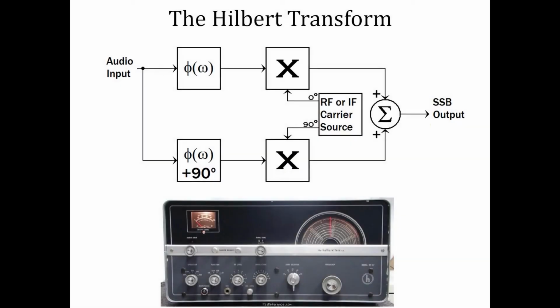It all has to do with the Hilbert transform. A Hilbert transform is an audio phase shift of 90 degrees for all audio frequencies. A Hilbert transform happens in every sideband transmitter, regardless of how the sideband is generated. And a Hilbert transform takes nicely peak-limited audio and turns it into a peaky mess with lots of sloppy overshoot. The RF envelope will be all over the place.